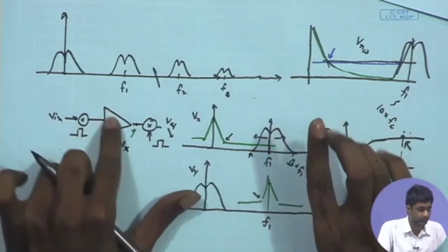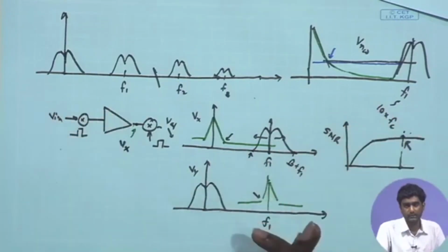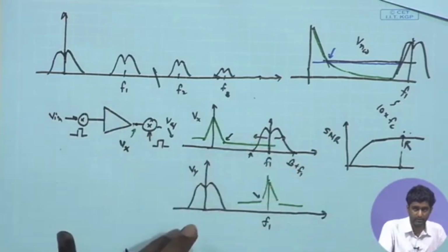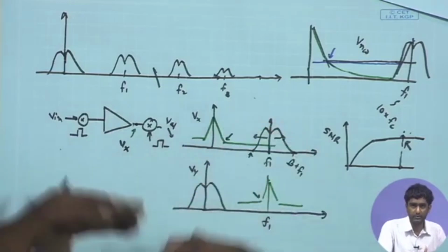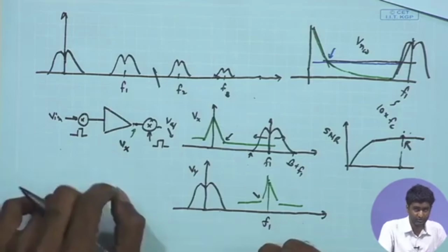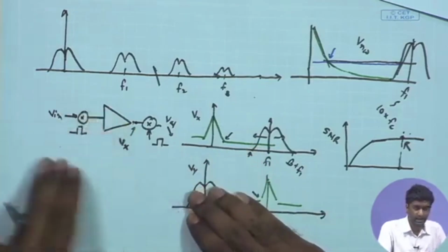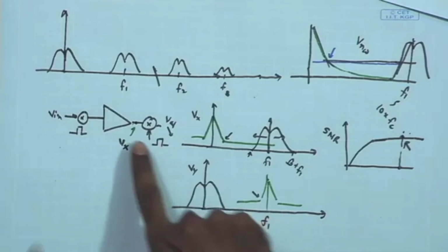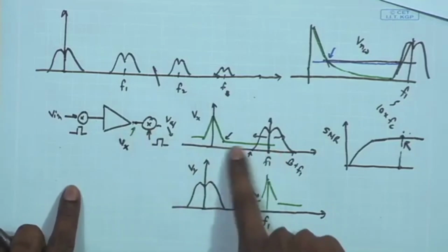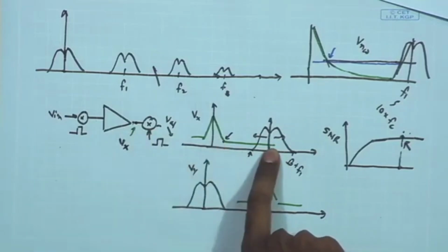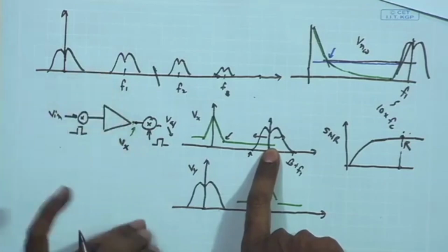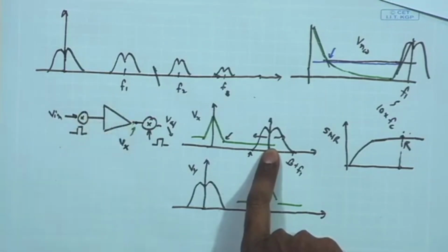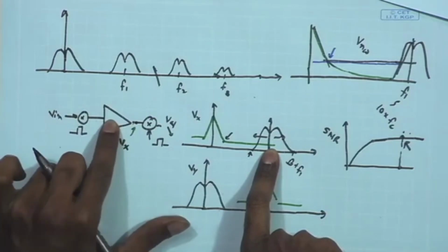but now if I am operating with a few kilohertz of chopping frequency, the cutoff frequency of this amplifier has to be a few kilohertz, and along with that you are going to have the constraint with the gain. So, you are increasing the bandwidth, the gain will be difficult to maintain. As a result, you will have to once again take care of the precision consideration, try to maintain the gain at the required value by looking at other trade offs like sizing, etc. So, for example, if you are trying to increase the cutoff frequency by say increasing the bias current, that is going to reduce your RO and hence increase the bandwidth of this circuit. At the same time, it is also going to reduce your open loop gain.